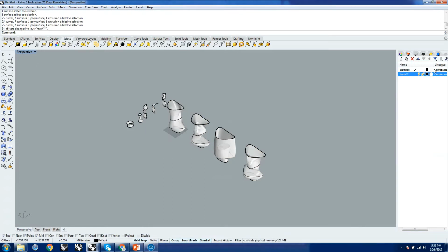Okay, so my default layer was the one that was ticked. So everything that I was making was in the default layer, and that's the workflow that I follow: I make everything on the default layer, and when I have to segregate them, I select objects and then put them in the right layer. This is similar to 3D modeling software and not similar to AutoCAD, because in AutoCAD you would probably be drafting or modeling in that layer itself. But here you draft, you model, you do everything on the default layer, and then you put it into the layers that you want to segregate it into.